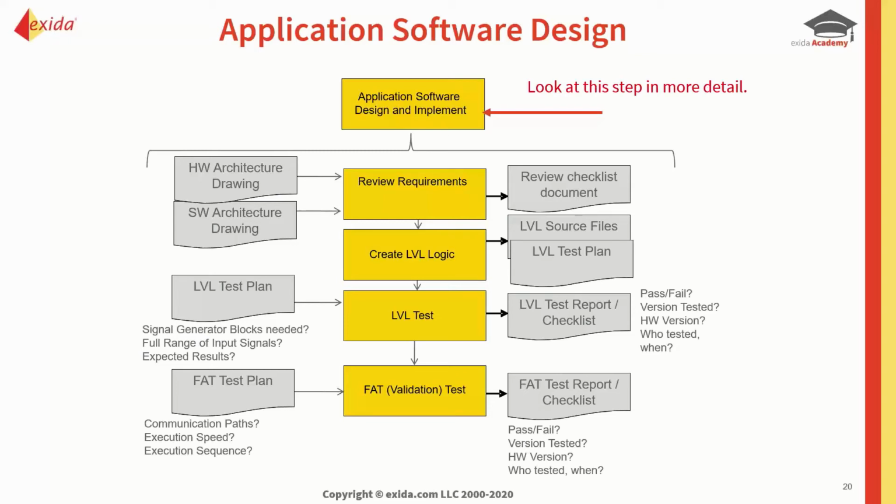Do we need any signal generators, or can we use tools provided by the logic solver manufacturer to provide the simulation that we need? Can we exercise the full range of the input signals? And again, what are we expecting as a set of results? So of course the test plan has to define all of that. And again, the test plan itself should be succinct, easy to follow and easy to implement.